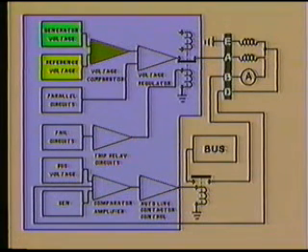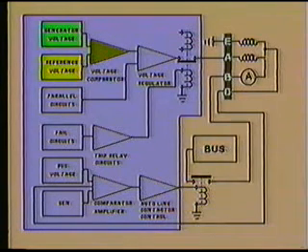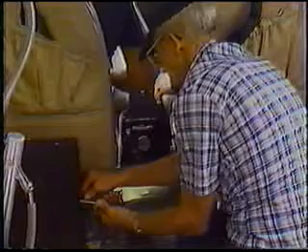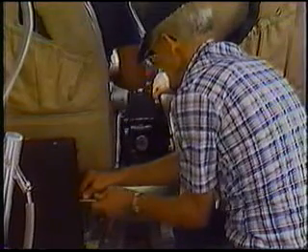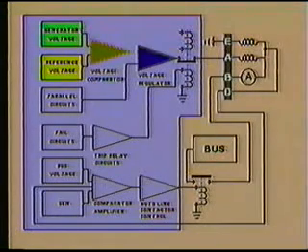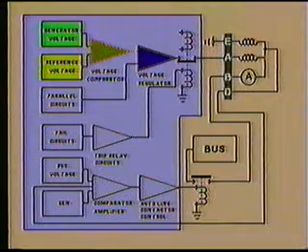If the generator output is above the reference voltage, the comparator will have no output, which will eventually cause the generator output voltage to decrease. The reference voltage is generated within the control panel and is adjusted during the generator paralleling process. We said that the voltage comparator would eventually affect the generator's output voltage. This is because the output of the voltage comparator must go through another stage, called the voltage regulator.